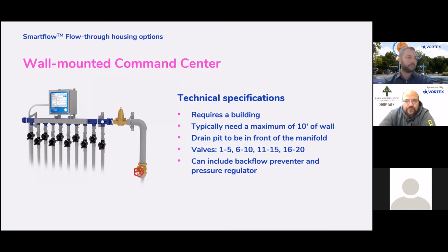Is there a minimum flow, other than otherwise you just get a trickle, or no, you can just push it up? It's not going to trickle at like 35 or 40 psi, but we're looking for 45 psi. 45, 50 psi, somewhere in that window is what we're shooting for.